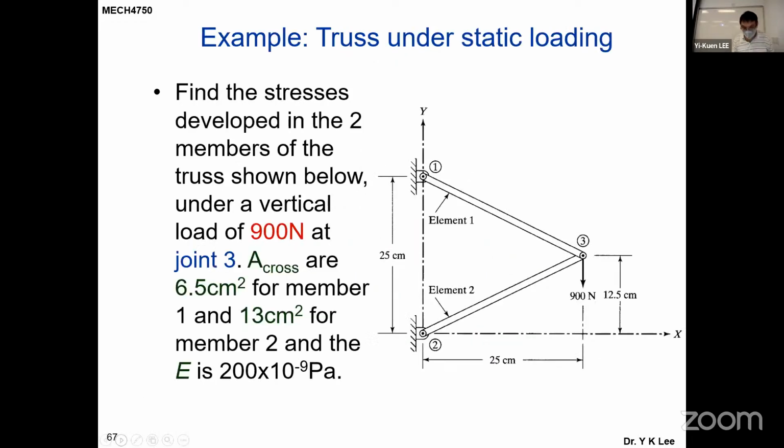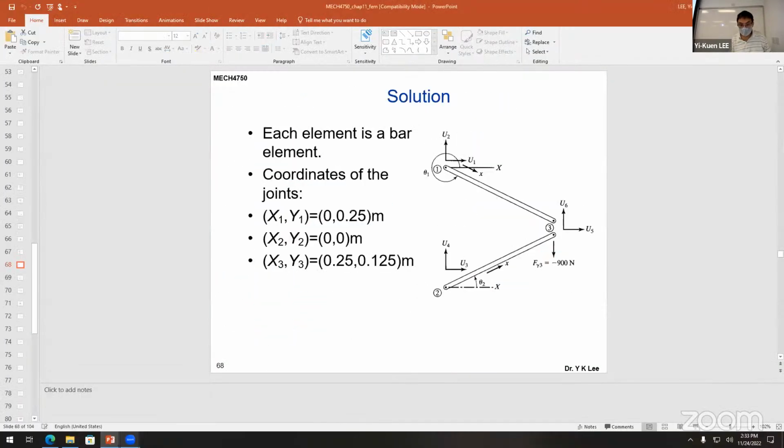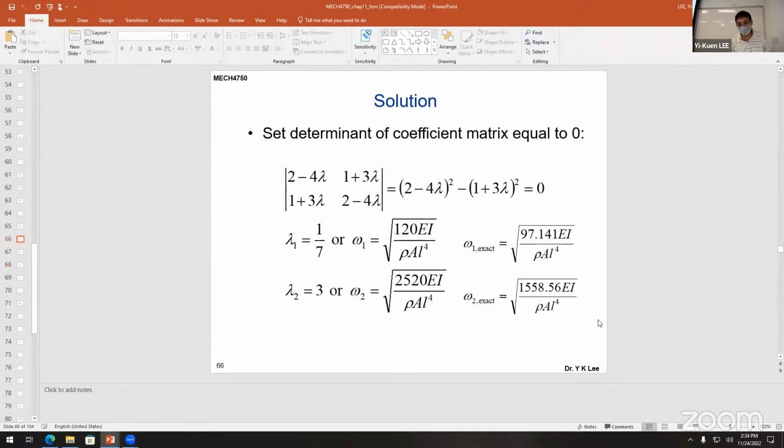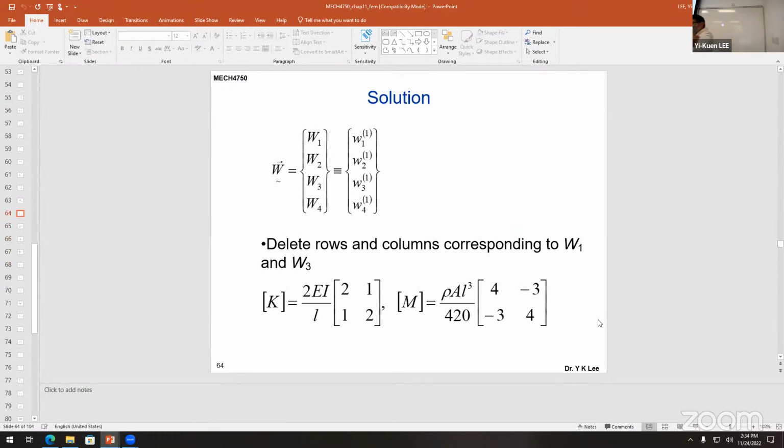Of course, I don't know if any of you have used this kind of commercial FEM software. Do you have any specific experience using SolidWorks or ANSYS? For a vibration problem, in practice with ANSYS or SolidWorks, the first thing is you need to really understand your mechanical structure, and then think about how to build a reasonable mesh model.